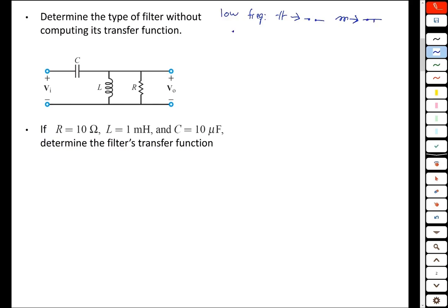So at low frequencies, basically, we get that open there. That is shorted out. You have a resistor there. And this becomes what the circuit looks like. And it's pretty obvious to see that because of this shorted out inductor, V out is equal to 0, regardless of anything else.